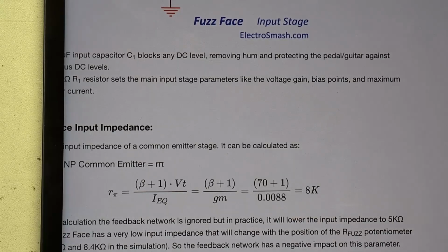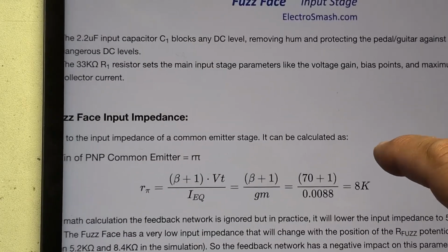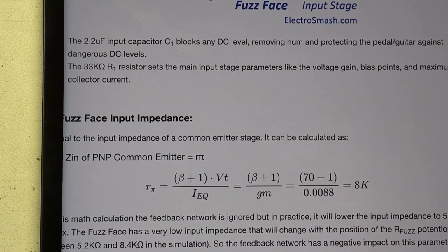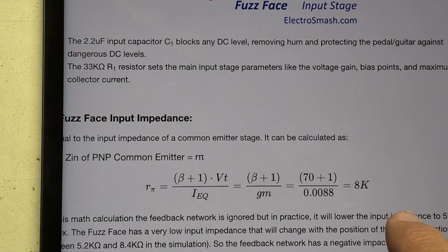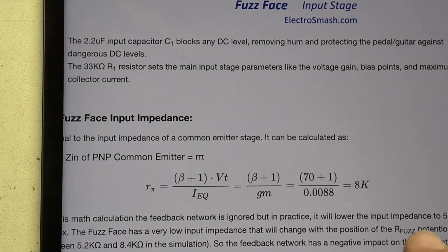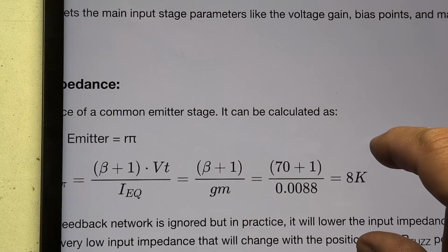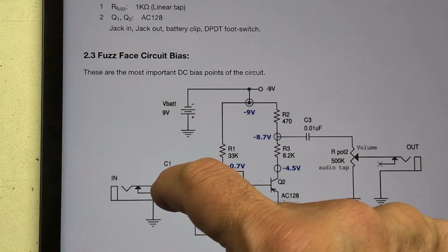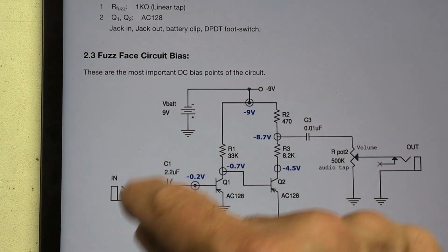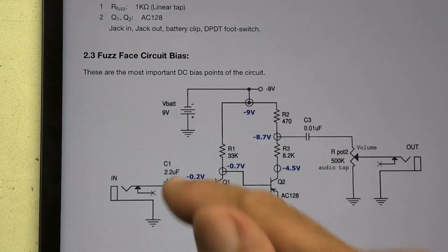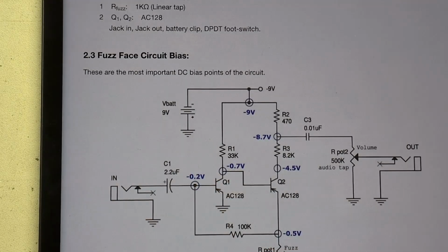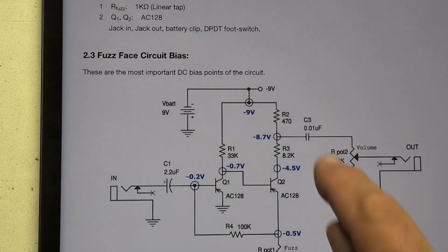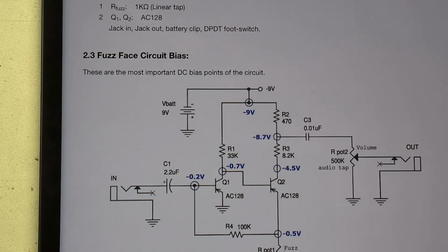And so when you play your Fuzz Face, and you modify the output of the signal or the impedance of the signal or the impedance/resistance with the pot, then it's really going to affect how this circuit works in terms of gain, because you're actually varying what, like a resistor set here, if you will. It's actually an inductor, resistor, capacitor set here on the front of the circuit, and that changes totally the gain characteristics of this.